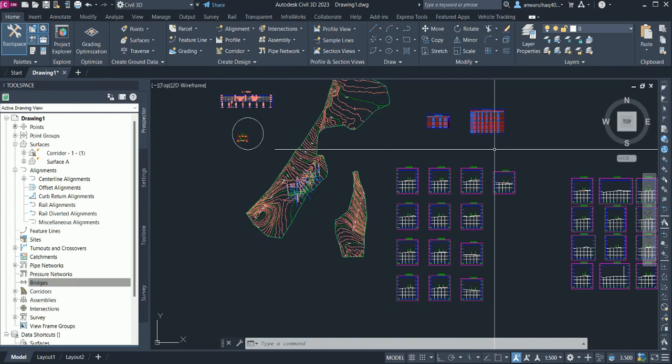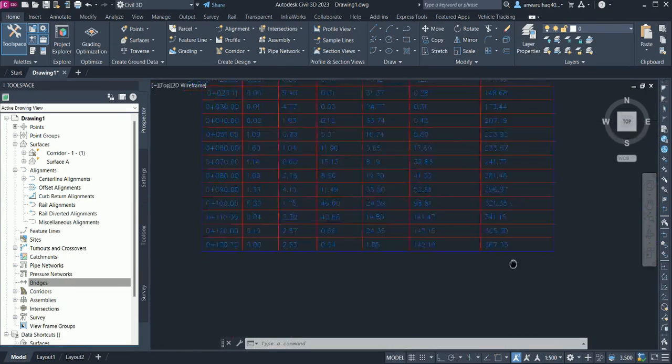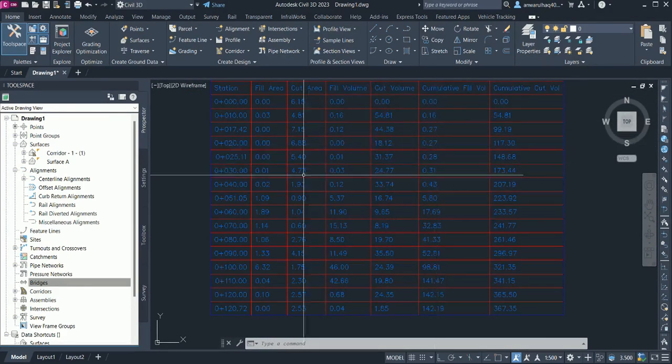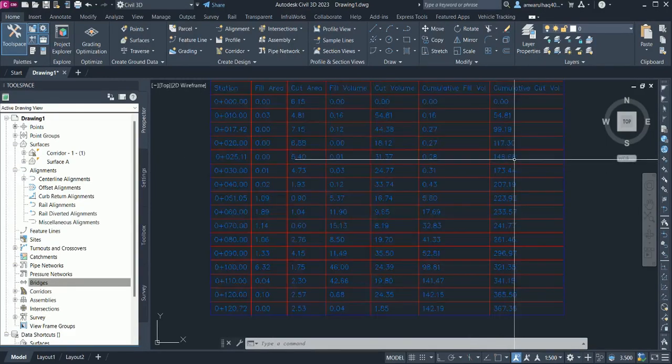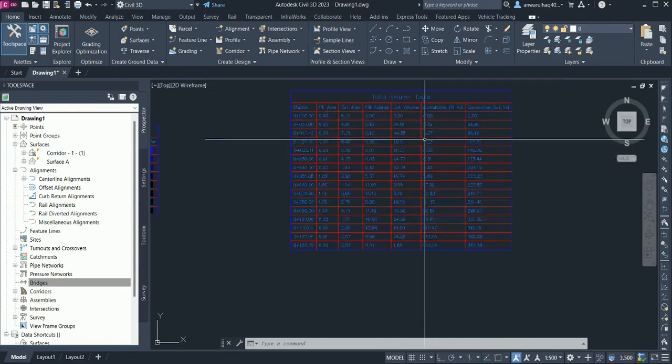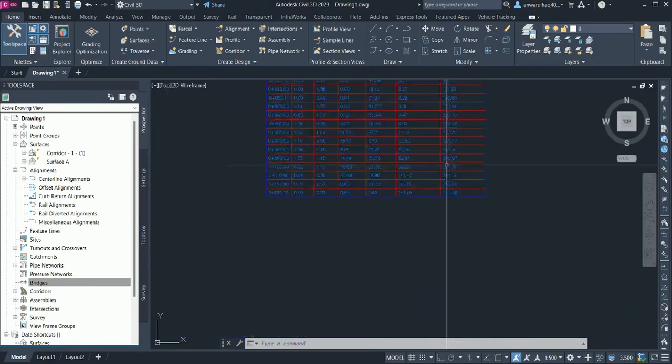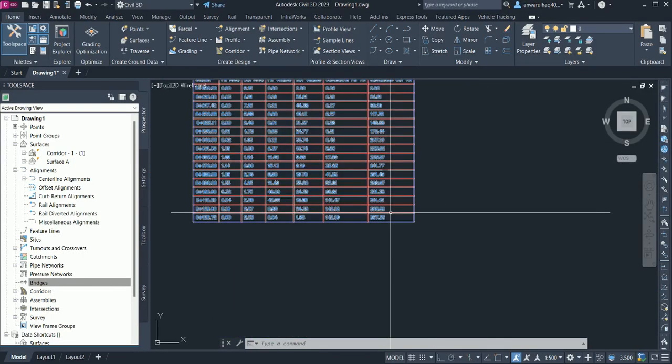After the cross sections, if we have road projects, normally we have cut and fill. If we have a channel project, first of all we have the excavation earthwork. It will be in the form of cut or in the form of fill. So you will come with this accumulative data. After the RD of 25 we accumulate this much, so we can find out our progress, we can find out our scope. So it is a very simple tool and very dynamic and accurate tool. The best thing of this software is that if your survey is accurate enough, the result will be accurate enough.